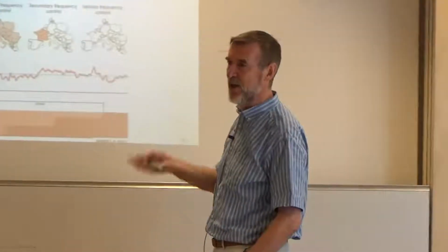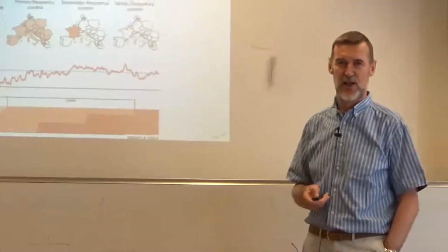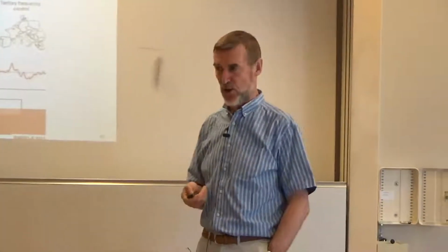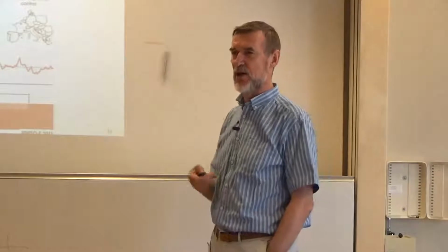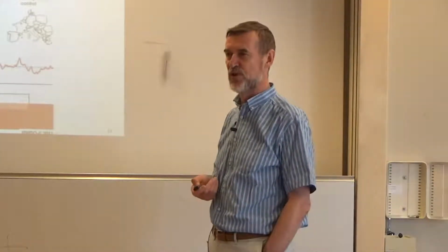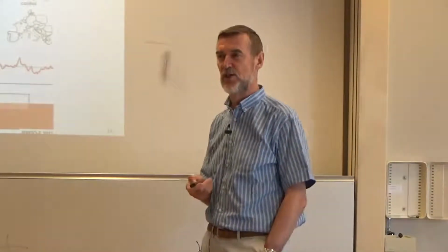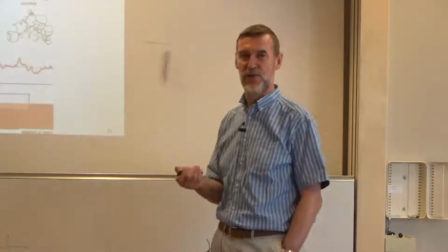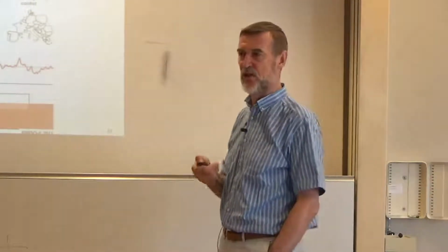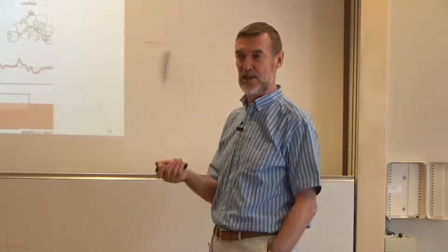There is a second type of reserve, which is called secondary, which operates on a larger time scale using explicit systems. So you have generators that are working only for this, providing a secondary reserve service, and they receive a signal, for example, from Swissgrid or other TSOs, and they have to follow this signal. So this signal tells them how much they have to produce, more or less. So it's an explicit signal.